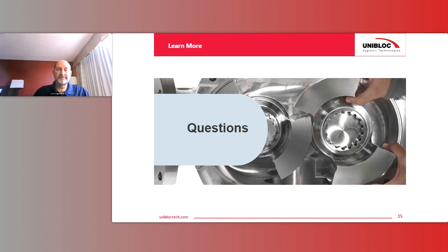Sounds good. The next question says, how can an AODD pump only have one nut? Okay, so as the slide showed there, it's due to the design of the pump itself. It's an inside-out design, so by taking that different take on the mechanical attachment of the pump, it has a center shaft that then can allow one nut to hold the whole pump together. So it's just in the unique design of the way it was done to be able to hold that together with one nut.